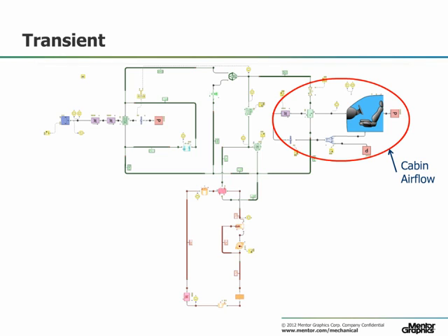Although the study discussed later on will assume the heater valve is closed, this circuit is set up to model the cabin controls a driver or passenger might have, including an adjustable fan speed, an option to recirculate air, a controllable heater valve, and an AC switch modeled as an evaporator heat load. The cabin volume itself will calculate a mean temperature over a characteristic length and is capable of estimating cabin comfort and reporting it in the form of percentage of people dissatisfied.